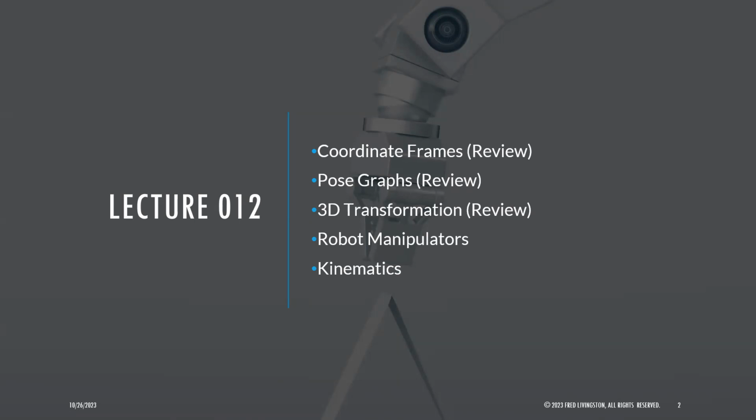And we talked about the pose graph, going from one pose, which is position and orientation, to another pose, and it's just going to be a series of transformations, which is going to be a dot product in linear algebra of 4x4 matrices. So if I want to go from my base frame to the tool frame, through the robot, I could go to the robot, and then go to the thing, and do the dot product. You still have a 4x4 matrix, and that 4x4 has the rotation component, a 3x3 matrix, and the translation component mixed together into a 4x4 matrix there.